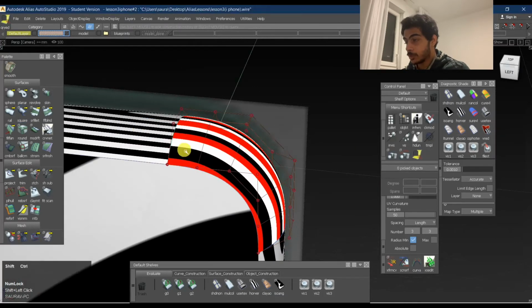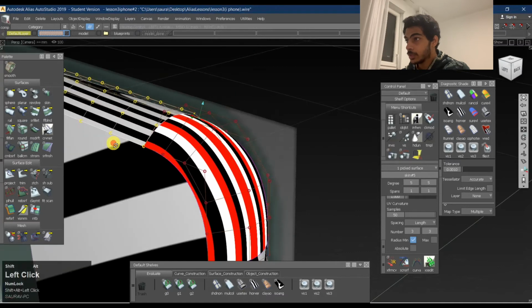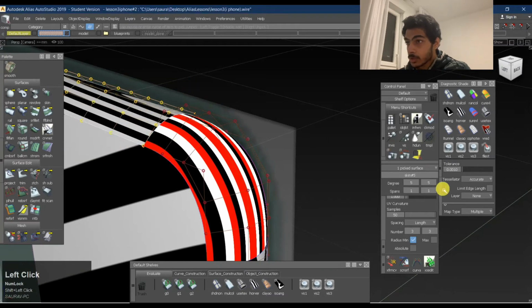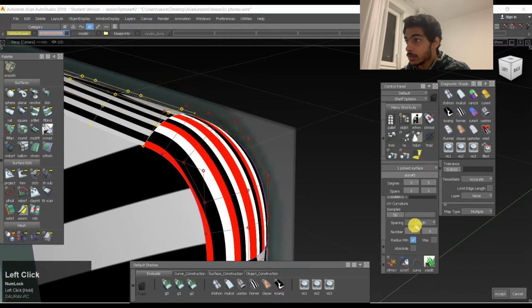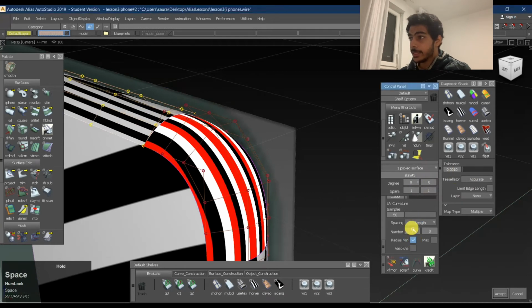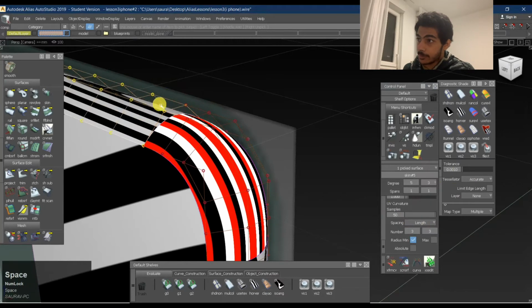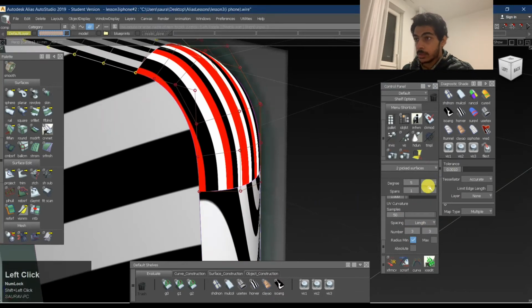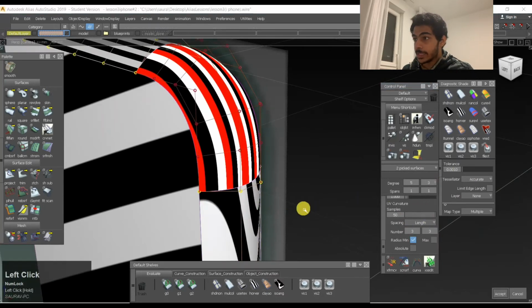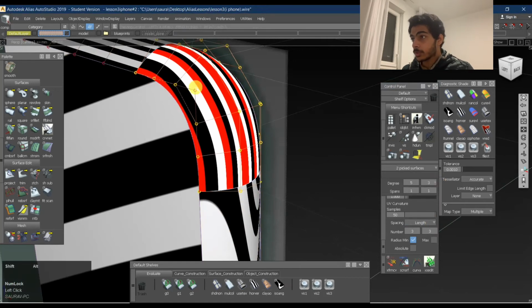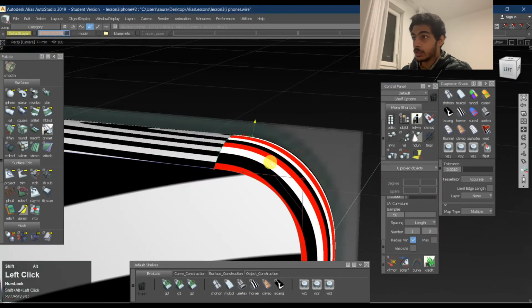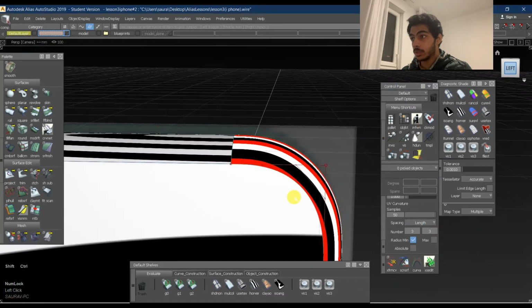I didn't expect it to be G2 over here, but it works. We'll keep this also into 3 degrees. So the thing is, I try to keep the degrees same so that it flows linearly, right? It's not changing a lot as well. The surfaces are not changing a lot, but we'll get more control over what we want to achieve, right?